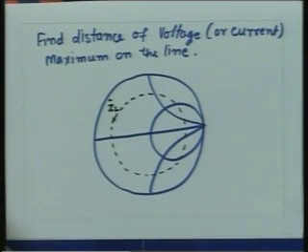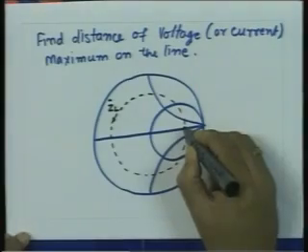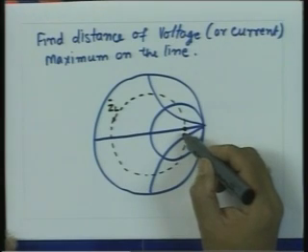Now, if you go back to your basic understanding of transmission line, we know that at the voltage maximum the current is minimum. So, at that location the impedance seen is the maximum impedance, which is nothing but R max, and wherever you have voltage minimum, at that location the current is maximum and the impedance seen will be R minimum. That means the extreme point, this point, corresponds to an impedance which is R max.